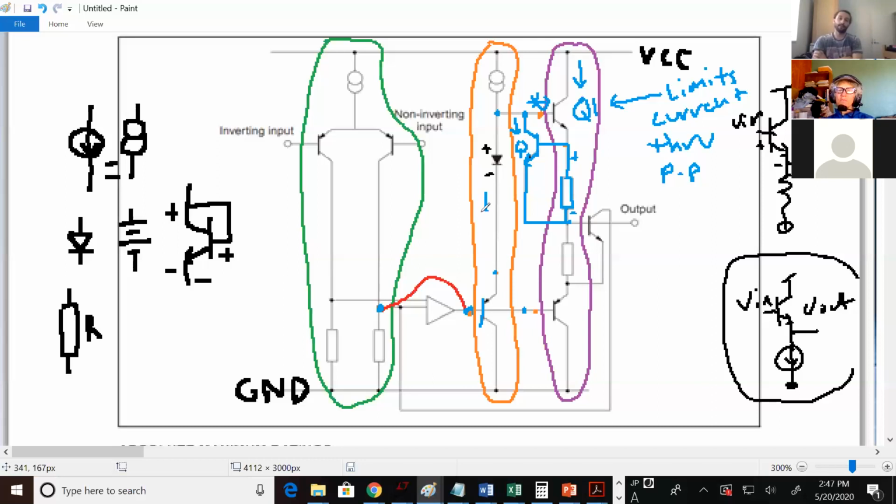I'm saying there's probably a little bit of extra circuitry here to keep this current relatively constant. Whatever this current is minus this, that's generally what's coming off of here. And either it all goes into the base or you pull some of it off. If this transistor wasn't there, it would all go into the base. But this one says, if too much ends up going into the base, then I'm going to pull some of that off, redirect it. Did that satisfy you?